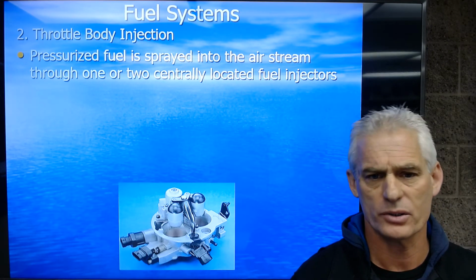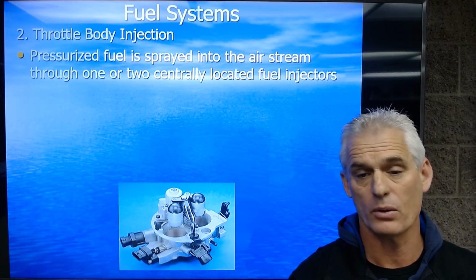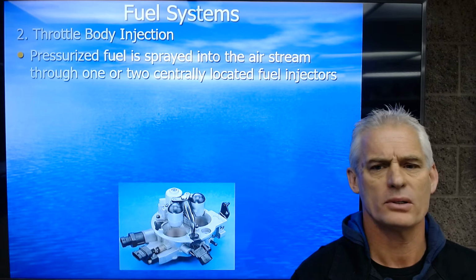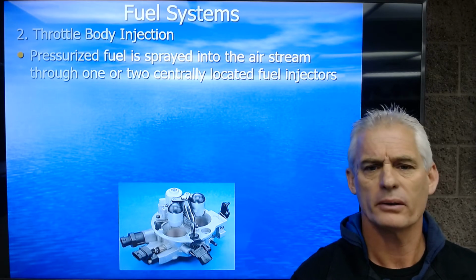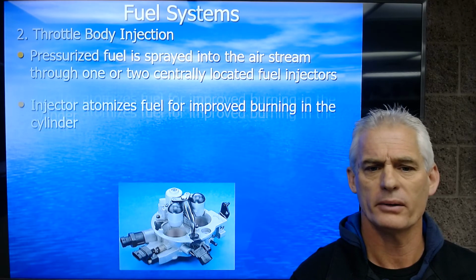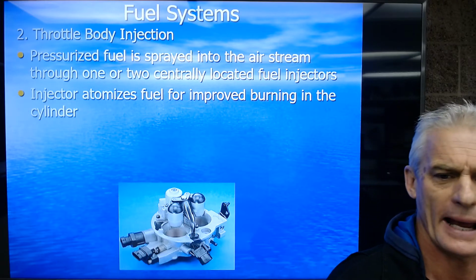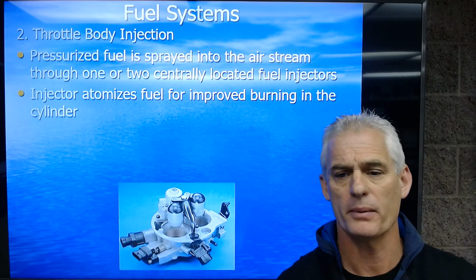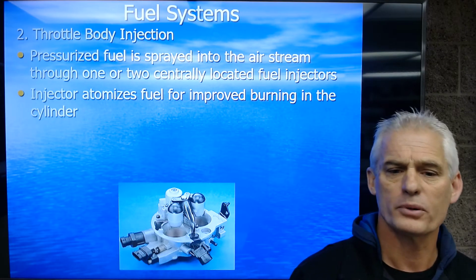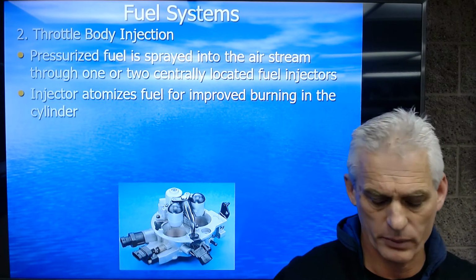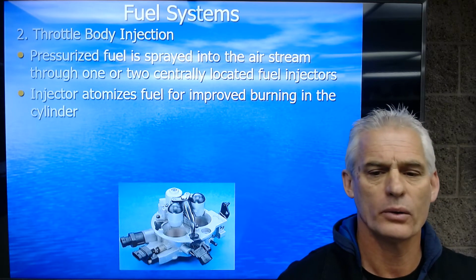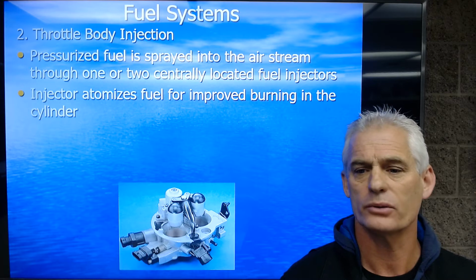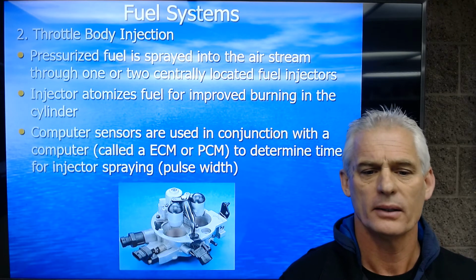Consequently, throttle body injection units have better drivability, especially when cold starting. Gas mileage and power is about the same as a carburetor, but emissions are better. Okay, so drivability and emissions are better. The injector is going to atomize fuel because it's sprayed out under high pressure, like the spray bottle I just showed you, for improved burning in the cylinder. By atomizing it, it allows it to burn better. That's true, so improved burning in the cylinder.